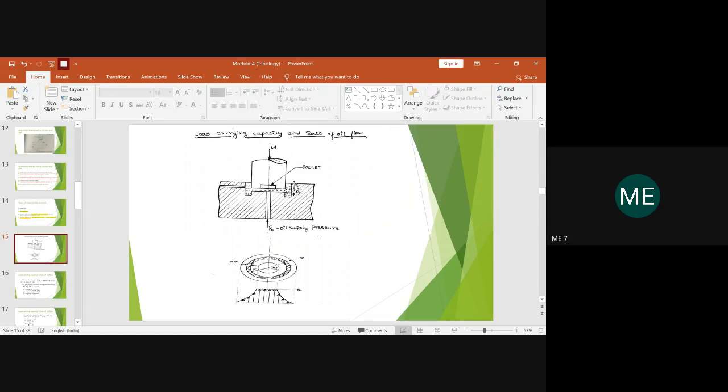The thickness of the oil film, you know, is usually represented by h. If it is h naught, that is the minimum oil film thickness needed. I told you already, a hydrostatic bearing has the least amount of friction, as it even runs at a speed comparatively lesser than that of a hydrodynamic journal bearing, and hence the friction will be less. We can consider a negligible amount of friction. Due to that, a very thin film of oil is capable enough to see that the journal runs smoothly with negligible friction, and at the same time it has the capacity to bear the weight applied to it.